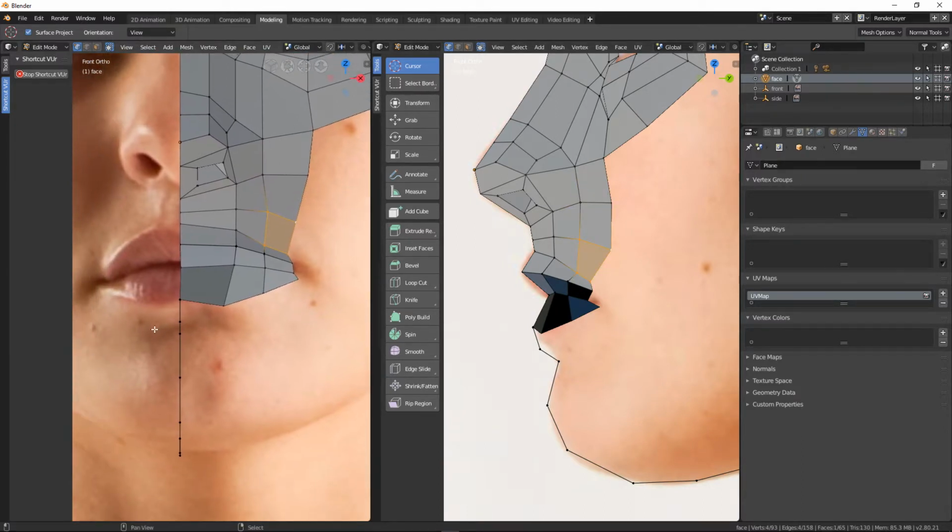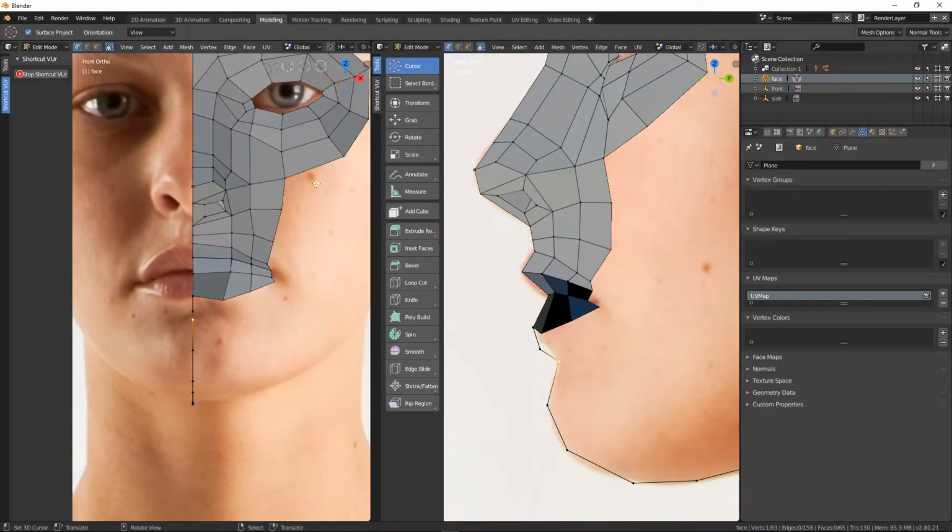is I'm going to take one or two verts here from where the chin is. So we'll start with this one, and I'm going to try and attach it around here to the side. So I've got the bottom of the lip, we'll sort that out here, but this one I'm going to try and loop up to maybe attach to here. And I'm going to try and match the amount of geometry I have sliding over towards it.